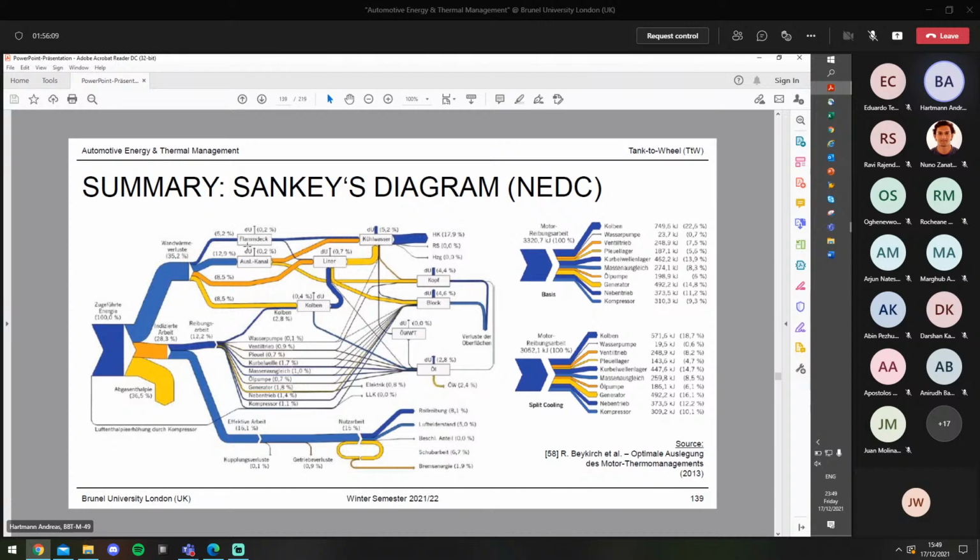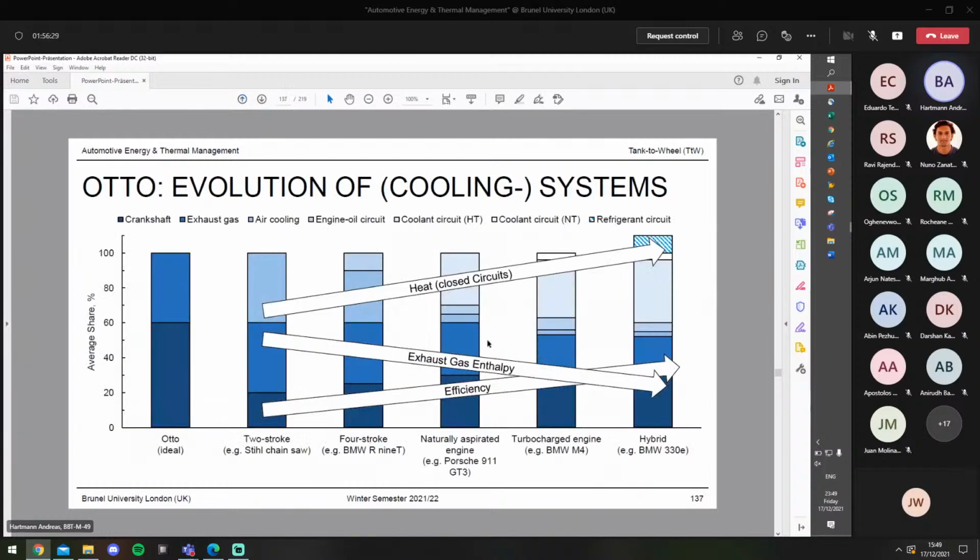You can check all the different heat flows, not only for the coolant itself, but also for the cylinder head and the crankshaft housing separately, and then this will lead to a way more difficult Sankey diagram. But I think for the scope of our lecture, the approach we've just applied is definitely sufficient. And the main idea is that you know how all the different energy flows are actually created, starting with the idealized Otto engine.